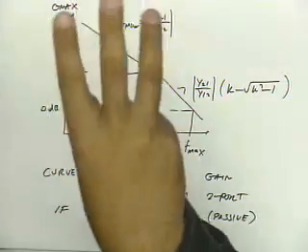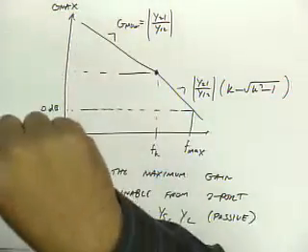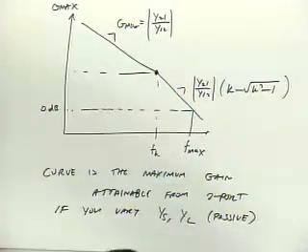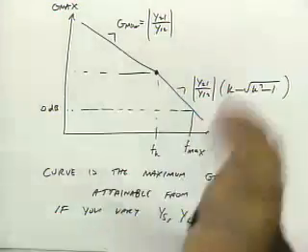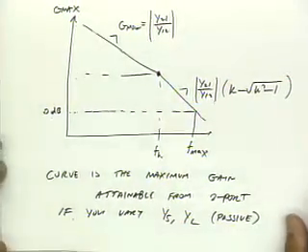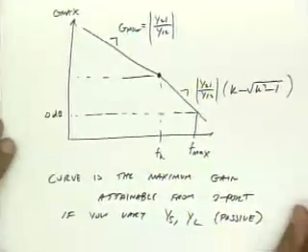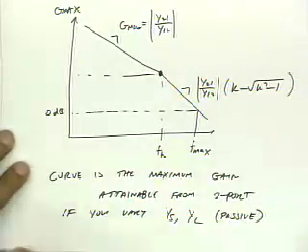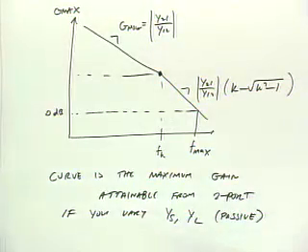So at very low frequency, your C mu is playing less role, but you have more gain in the device. Strictly at DC, you're right. The device is unilateral. Okay, very good point. You guys will have a homework assignment where you'll take a real device and you'll plot K as a function of frequency and you'll plot these gains as a function of frequency, and you'll get some intuition for it.